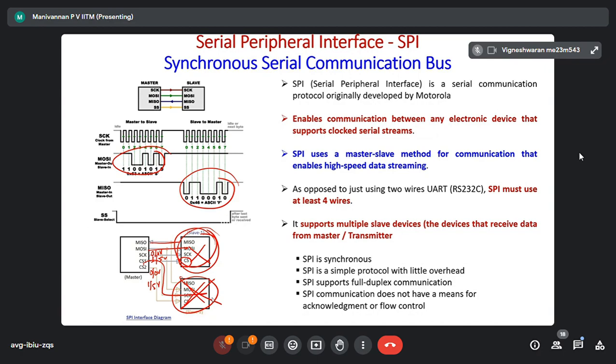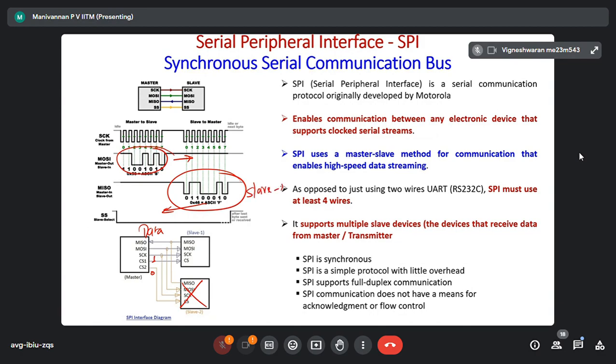Why? The master clearly says, if the master wants to send the data to slave 1, it will select the chip select 1. This is 1. This is 0. Automatically, this fellow cannot receive data, cannot give reply. This is reply from the slave. Master is asking some data, right? By sending this command, and slave is replying this. Master is sending this. Slave to this is from slave 1. Correct? Slave 2 cannot respond because he has not been selected by CPU at all.